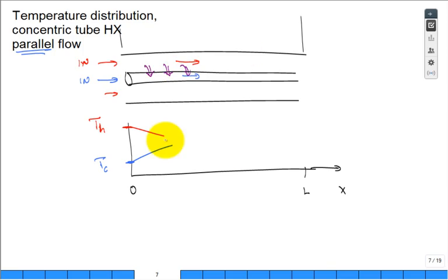Can you get a heat exchanger where the hot comes out at a lower temperature than the cold comes out? Well, in this section, you would be having heat transfer from the cold to the hot. Makes no sense. It would violate the second law. Cannot happen. Impossible. Right? So what's going to be the lowest hot out that it can go? The lowest would be the highest of the cold out. Maybe you had a super long heat exchanger.